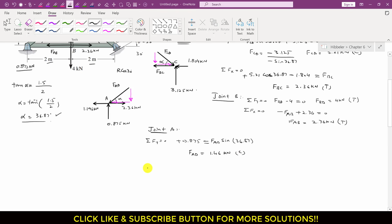And similarly, if we apply the summation of forces along x equals to 0, as we can see that 2.36 kilonewton force is acting in the positive direction, so this is 2.36. This is acting in the negative direction, so I will write minus 1.196, and this component of FAD is acting in the negative direction, so I will write minus. FAD magnitude is known, so it is 1.46 cos of alpha, which is 36.87, and this is equal to 0.